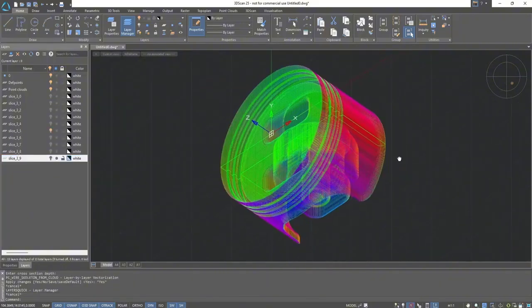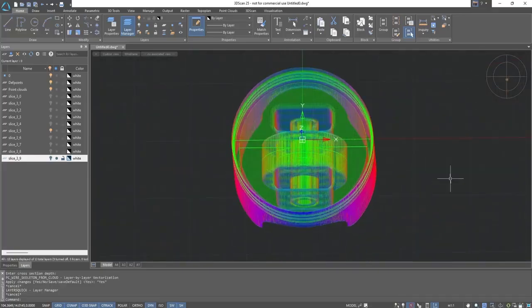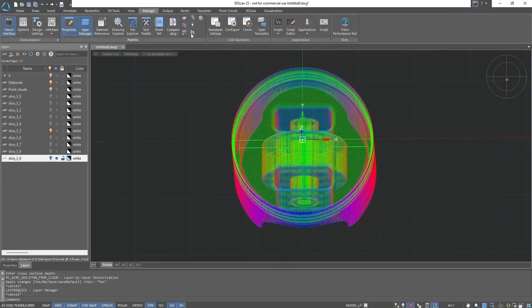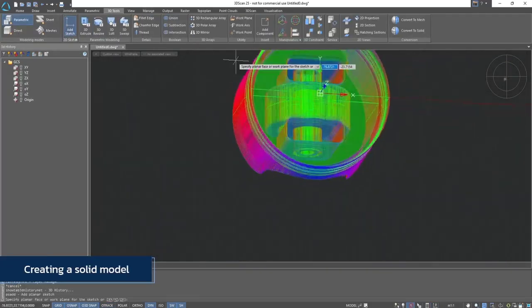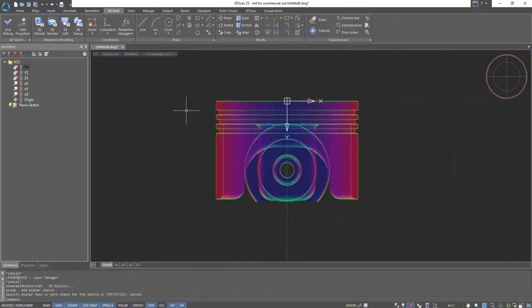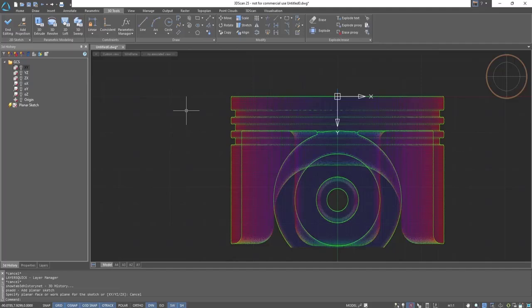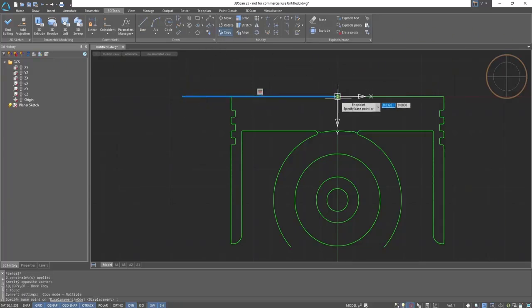At the moment, it is important for us to create a contour that will circumscribe our piston and will be a general-purpose primitive without additional details. So we will now begin to create our sketch. Turn on 3D History. Let's draw a general outline based on the created polylines. I suggest hiding the point cloud for convenience. Now you can draw it not very carefully, and then we will clip the contours to get a contour for rotation.